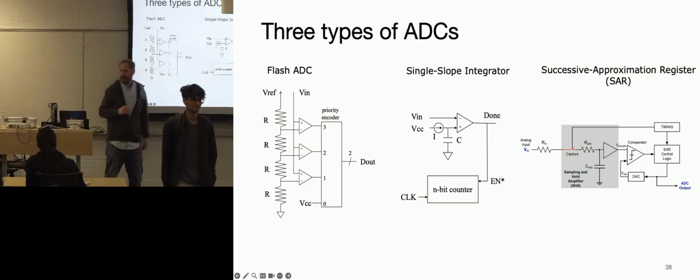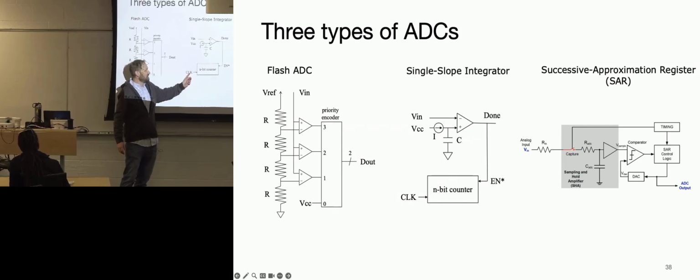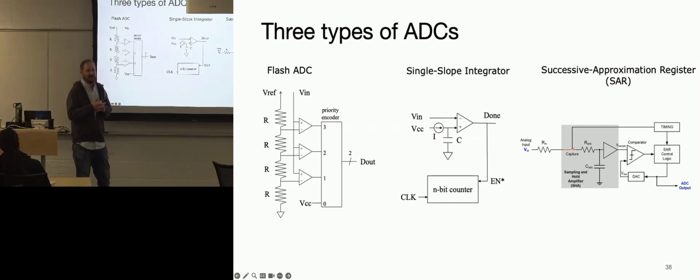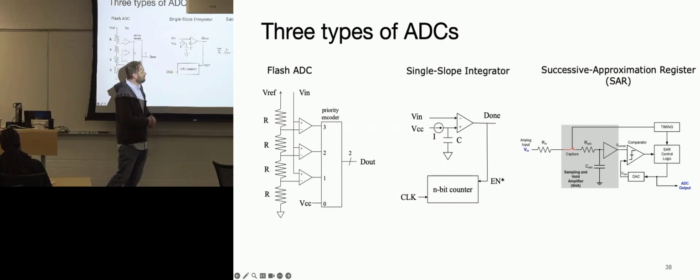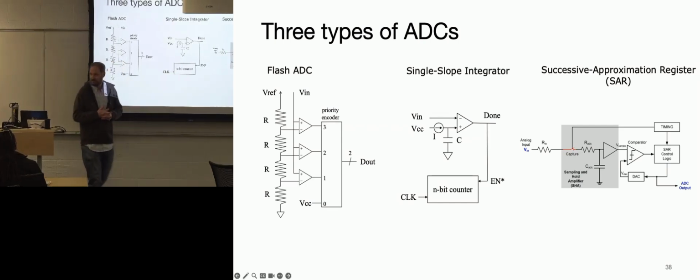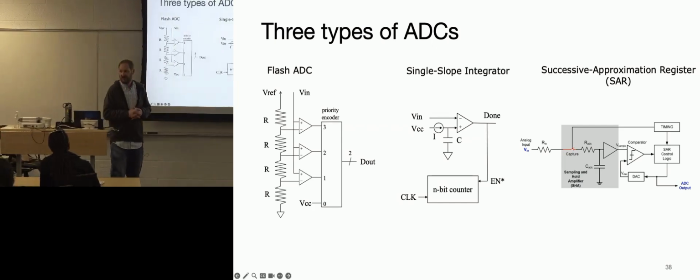And this is nice because now you can change your clock and get higher resolution. That's kind of cool, right? Because microcontrollers are really good at time, and they're bad at everything else. So this is an example where you're using the right measurement form factor that your machine is really good at. Was that a constant current source? Yes. A capacitor that makes the voltage go up linearly? Correct.